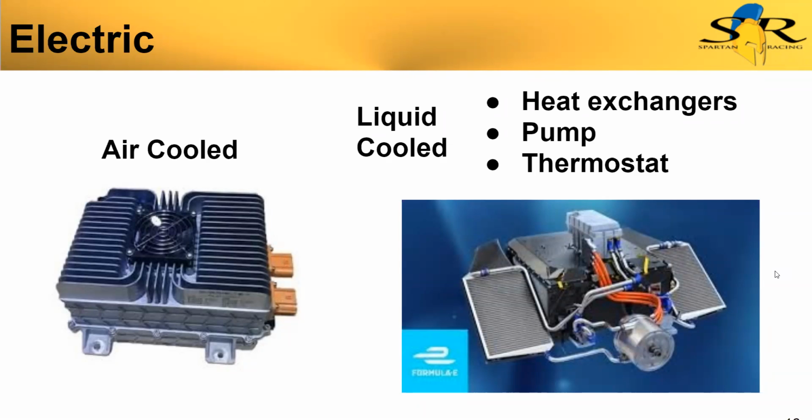Or you can use that to your advantage as far as the different flow rate, to channel lots of flow to your components that need to reject a lot of heat, and just a little bit of flow to the components that maybe don't need to reject as much heat. But it is really complicated and easy to introduce problems with parallel flow systems for that reason. Got it. Thank you. Yep.